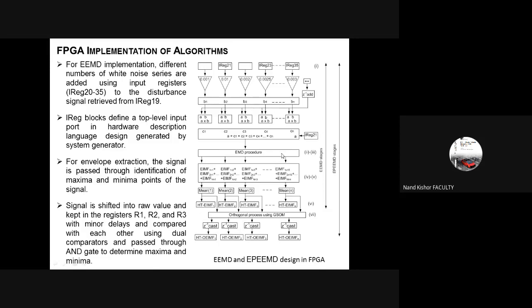That means the EMD approach, that means decomposition into IMFs. And then we take the mean because we want the upper envelope and the lower envelope, all that part we do. And then last, we apply the Hilbert transform on each IMF here. So up to this stage, this is actually the EMD technique. Then